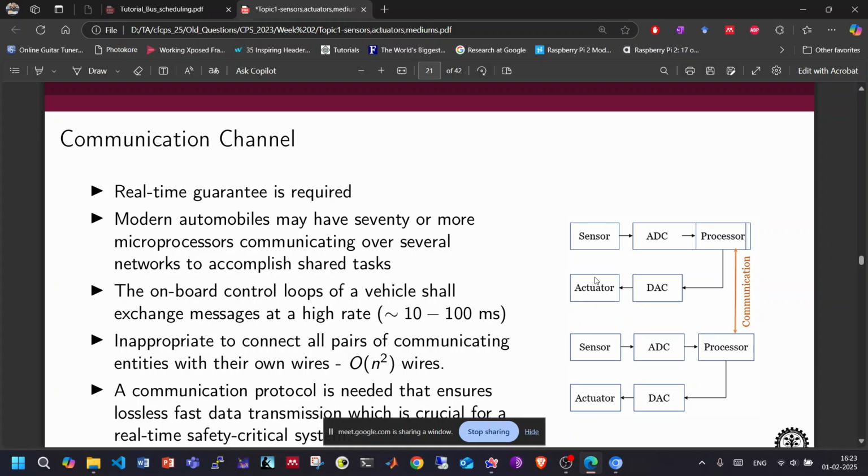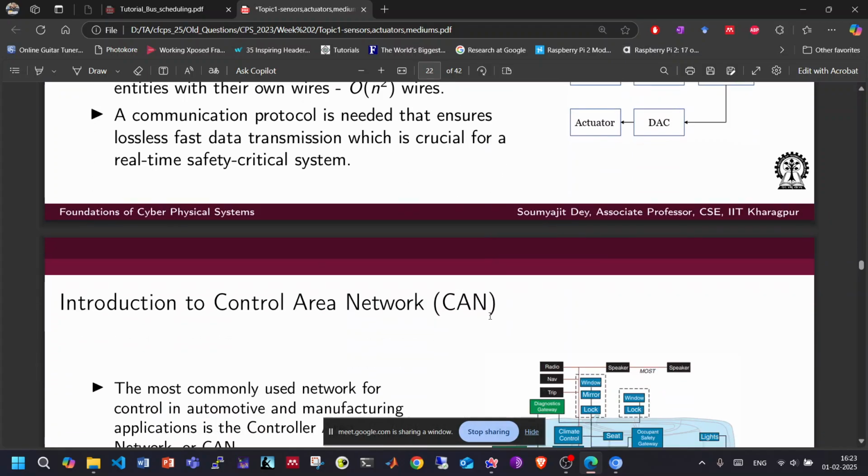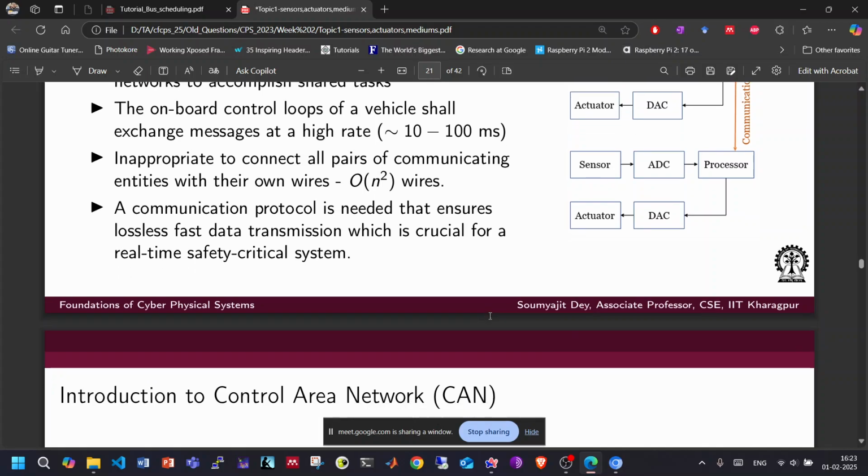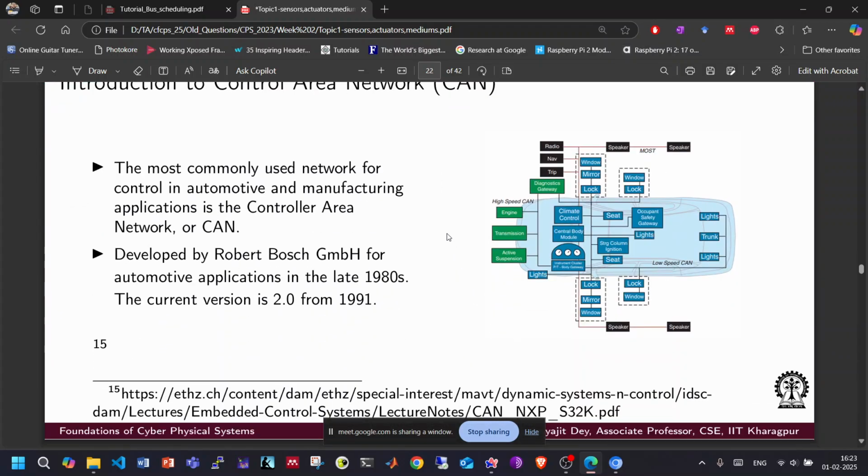Since we are trying to convert a continuous signal to a discrete time one, we have to sample really fast, like in the millisecond range or maybe 0.1 millisecond range. If we sample that fast, then the data also has to be communicated that fast. For that, the communication protocol has to support fast data communication without a very heavy implementation.